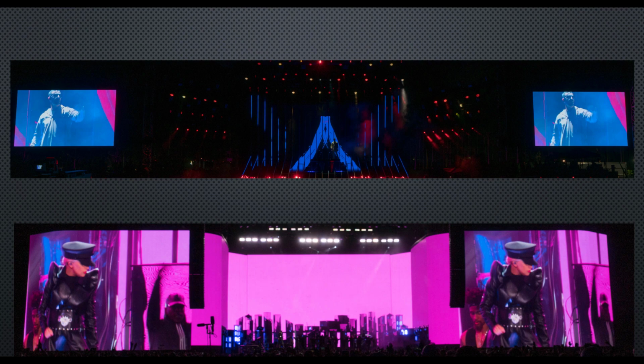And that's what we had to do using, again, a Barco E2 switcher, which is now possible using Nova Pro Ultra HD Junior with multiple layers of windows. And in the bottom picture, you can see we've still maintained 16 by 9 aspect ratio and scaled it up to fill top to bottom and cut off a lot of image side to side, because that LED screen is, again, not 16 by 9.